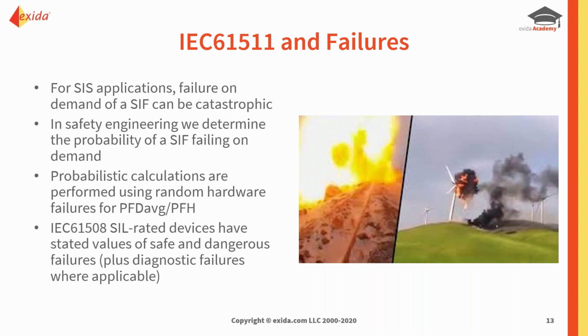So from a safety engineering point of view, we have to determine the probability of a SIF failing on demand. It's the probabilistic calculations that we need to do. And these probabilistic calculations are performed using random hardware failures for our PFD average and our PFH. For SIL rated devices, these will have stated values of safe and dangerous failures. And if they are intelligent and have some diagnostics, there will also be diagnostic failures stated.